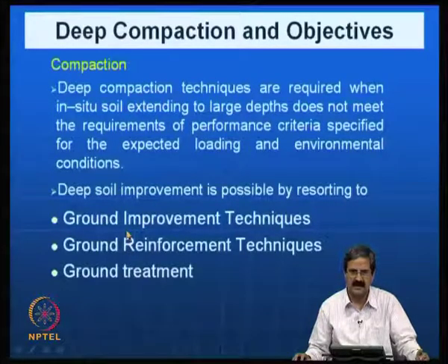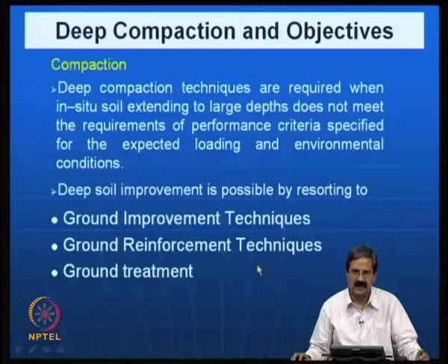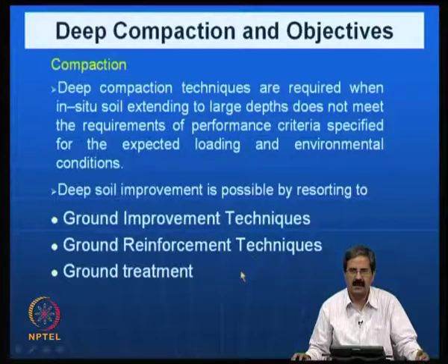First, deep soil improvement techniques, where one can use many methods like stone columns, jet grouting, deep mixing, and many other methods that we will be discussing. Then ground reinforcement techniques are also possible, where you have micropiles, use of geosynthetics, then even stone columns, many things that use the reinforcement function as the main criterion for improvement. We classify them under ground reinforcement techniques.